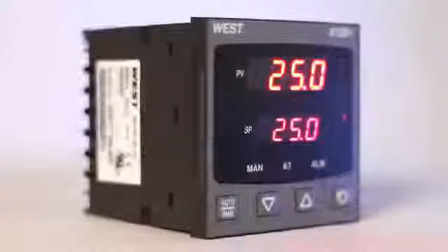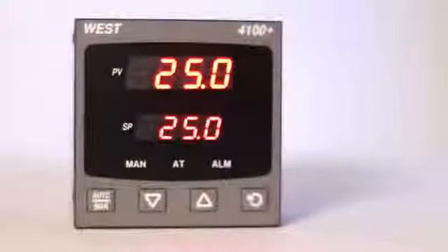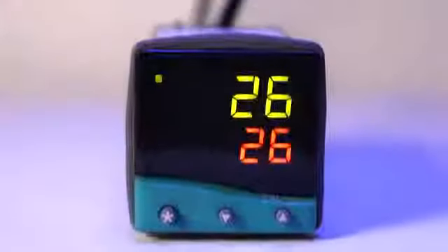So you can use a deviation alarm to warn you if your process is getting too high or if it's getting too low. But what if you wanted to know if it was too high or too low? If your controller has more than one alarm available, you can set one up as a deviation high alarm and the other as a deviation low alarm so that you'll receive a warning if there is a problem in either direction. If, as in the example I just gave, you wanted alarms at 225 degrees and 217 degrees with a set point at 220, this is exactly what you would do.